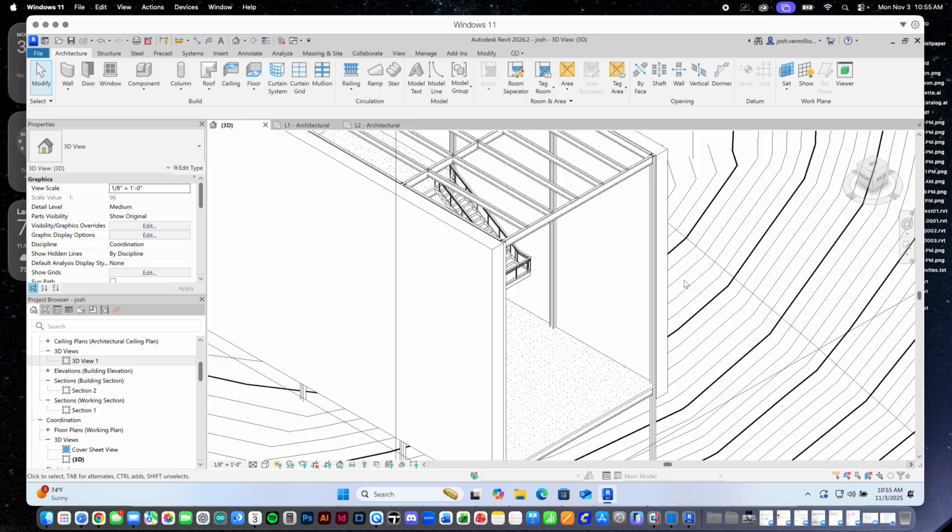What we'd probably do then is make a plate that follows the cavity around that flange all the way up, and then we would frame to the bottom of that beam and the sides of the columns, and that would be our rough opening. And of course, if we think about this for a moment, we place a curtain wall in there, and that's glass and aluminum, and then we have a steel frame around it, right? So we build in, what do you call it?